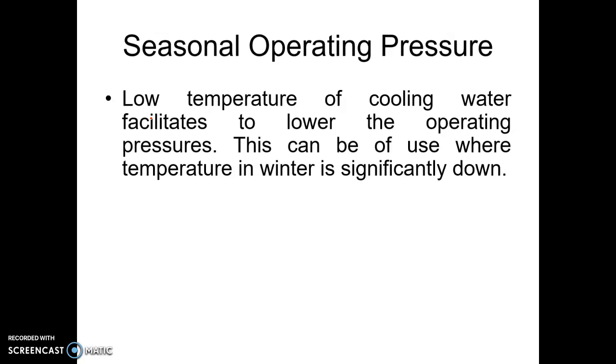So decrease the pressure of the column, let the temperature of the condenser go down, but by decreasing the column pressure, your VLE will be favoring the separation, and the required reflux ratio will go down because the number of stages is fixed. So if the number of stages is fixed, decreasing pressure will naturally directly impact your reflux ratio, which will go down, and this will lead to a lesser amount of reboiler and condenser duty.